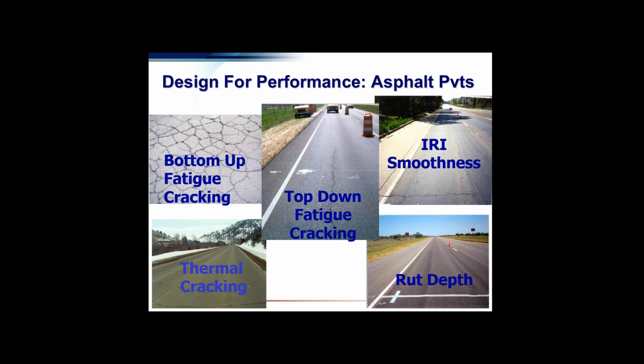But other than that, temperature and moisture are considered in these others, but there's other distresses that create problems and require maintenance that are not involved in this design procedure. How do you handle them? Through specifications. You try to specify asphalt binders and gradations that will not block crack and ravel and strip. On the concrete side, you really want durable aggregates. You want air entrainment.